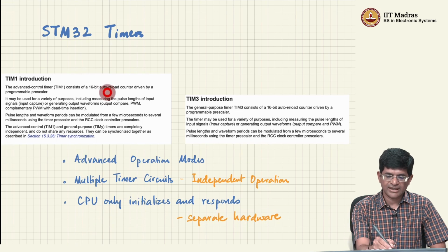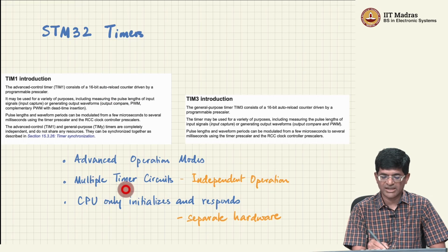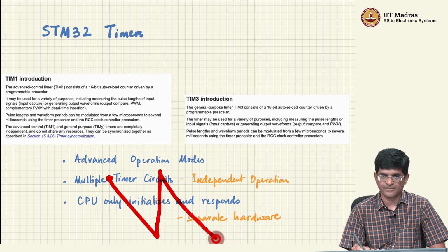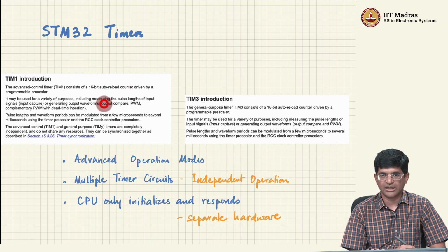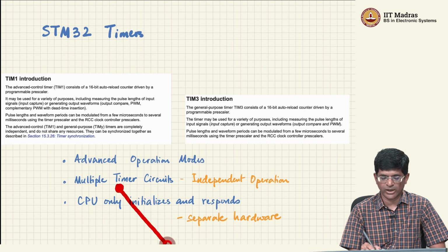And this resetting can also be done in a certain way where you could also have it as a down counter. It basically starts off with one value, counts down to 0, and then again goes back and counts again, meaning that it can even automatically reload the value that you want it to start from, right? So you could either have a compare value where it basically stops and then comes back, or you could have an automatic starting point and then count down and then flip up again.